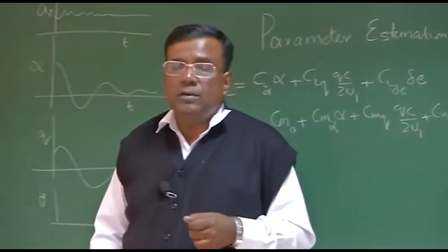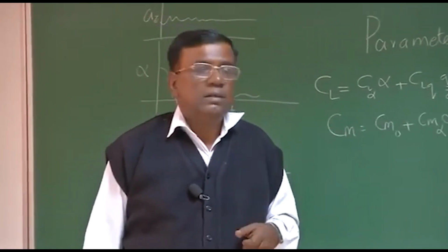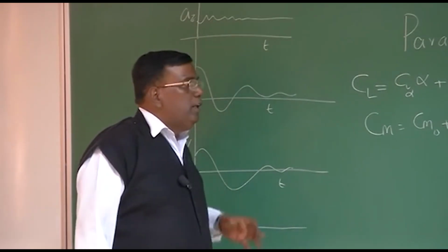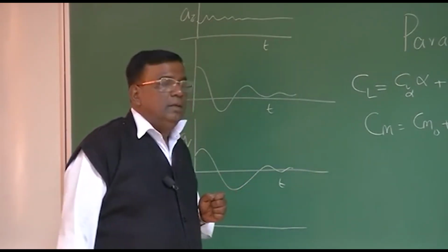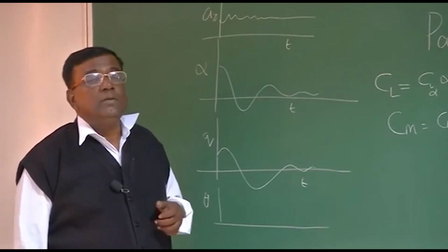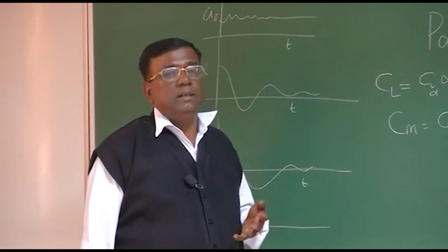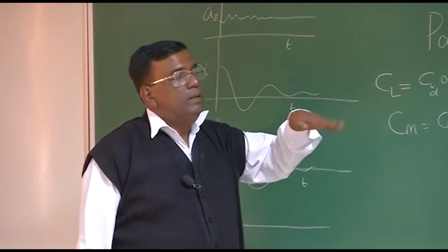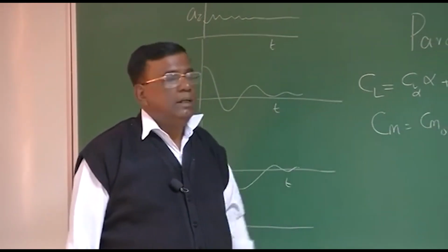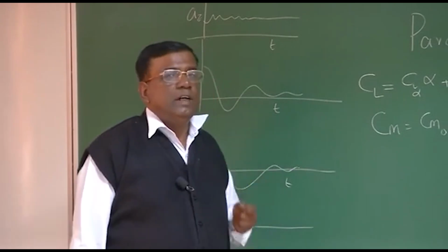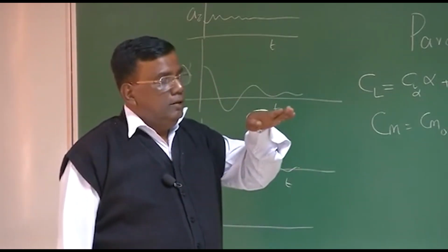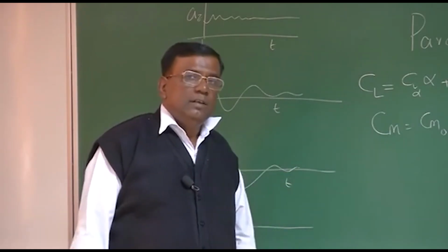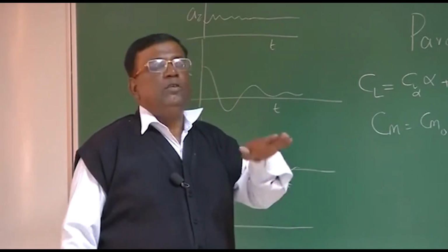Should I give a pulse? Should I give multiple pulses? Should I give an impulse? So how to understand what I should do? For that, the first thing you should not forget is, what is the natural frequency of the airplane you are testing? Rough estimate. Suppose the short period frequency is, say, 10 Hertz. Then you try to give an input in such a way that the excited frequency of the airplane is around 10 Hertz, so that the longitudinal short period will be really excited.